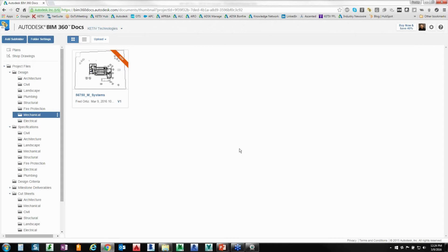Well, it extracts pretty much every sheet that you have set up in there. So if there's a dummy sheet that maybe isn't populated, once you go through the extraction and publishing of the documents, you could always go through and delete that one from that file. It will extract every sheet tied to that model. And if there are ones you don't want, you just simply go in there and delete it. Clean it up at the end.